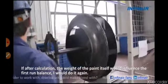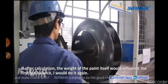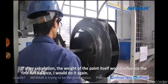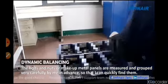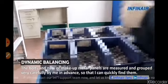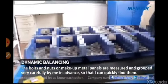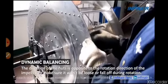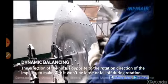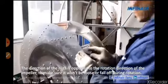If after calculation the weight of the paint itself would influence the first run balance, I do it again. The bolts and nuts or makeup metal plates are measured and grouped very carefully by me in advance, so that I can quickly find them. The direction of the nuts is opposite to the rotation direction of the impeller, to make sure it won't come loose or fall off during rotation.